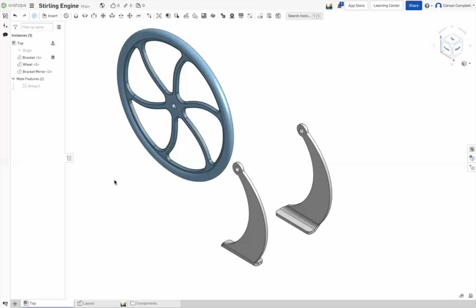Onshape allows you to inherit mates from lower level assemblies. And by mating to assembly features, you break that chain. Therefore, let's turn it all off, and you are not allowed to use any geometry in the assembly to construct these parts. It's a mighty big order, and it's much different than SolidWorks. SolidWorks, they don't care, but it'll damage Onshape.